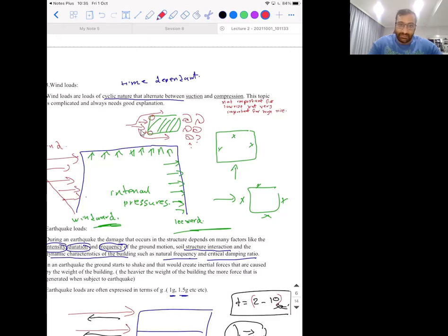What happens is these are going to hit the building and react on the surface of the building and get distributed throughout the building. But we have winds that come around the building through this corner and through that corner and go back to the building and cause what we call vortices. So these are vortices. These vortices are very important when designing skyscrapers.